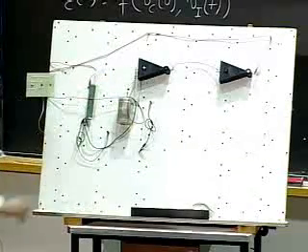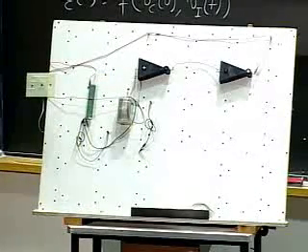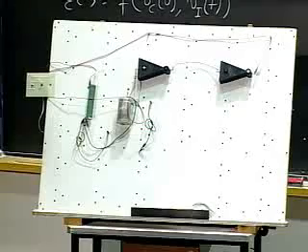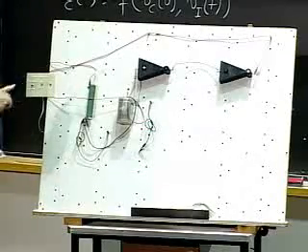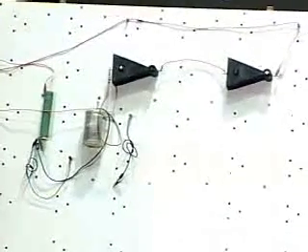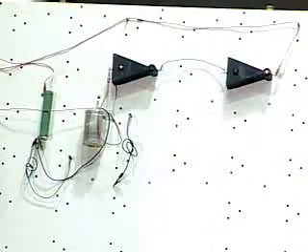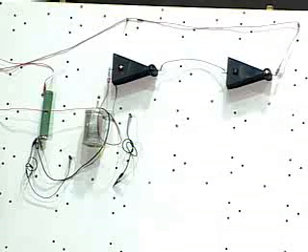This dimmed a little bit, but the output has remained okay. All right? So we've provided a feedback. Now we've created a static memory. This will hold charge for as long as the circuit is powered up.